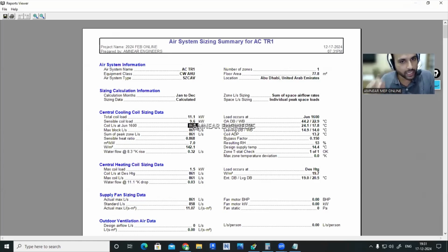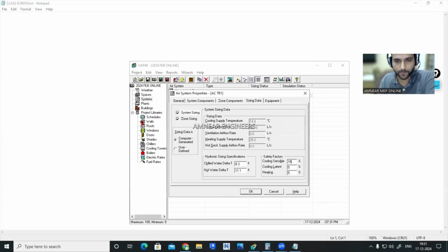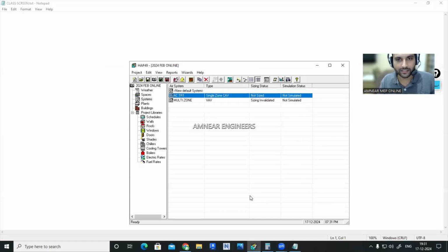The heat load that is generating is with respect to the internal and external conditions, so you should not adjust that. A 10 to 15% safety factor is required. So don't do that. That's why, simple thing. No?